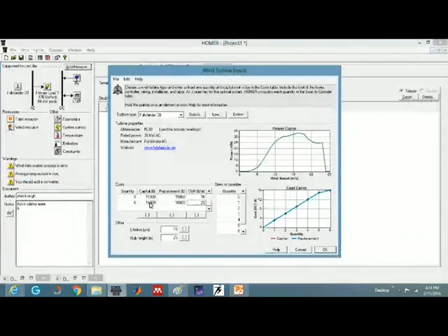Again, here we have given so many variables: lifetime, hub height, everything. How many quantity do I have to consider? It's up to me. Let's say I want to keep it up to 6. I don't want to use more than 6 turbines in this system, so I can put a cap. Suppose I want a hybrid system where I will have only one turbine. So the limitation is there, and here I can give the limitations. Now it will simulate only for one turbine.